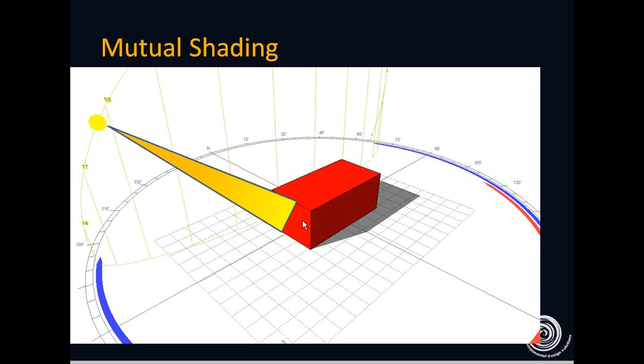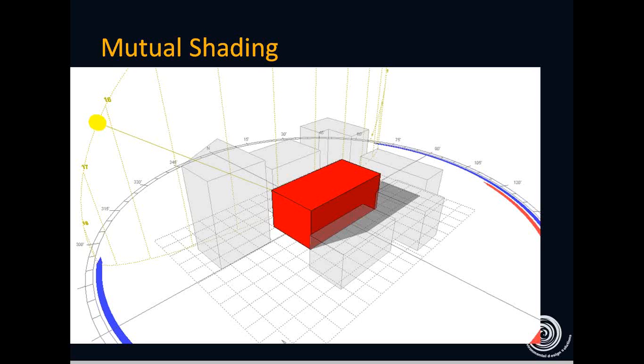When the surrounding buildings are modeled, the sun is modeled. So if you can now see in the slide, this facade is protected from the sun by the surrounding building. So now the recommendation changes. Now we should go with more windows on this facade, and we can go with a less performing glass, low performing glass.